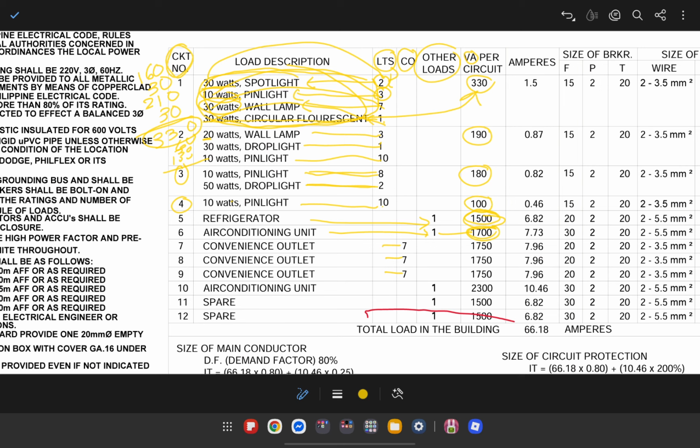And so to make sure that it is evenly placed on each circuit, I just divided it into 3. So there is 7 for each. Each outlet will have roughly 250 watts. It means that each outlet has the capacity to accommodate a 250 watts load.